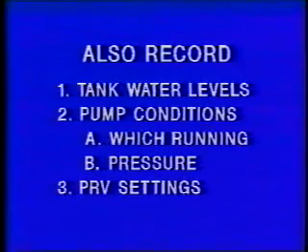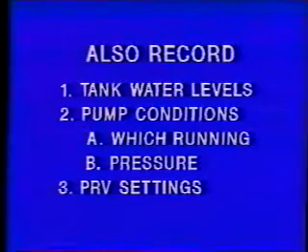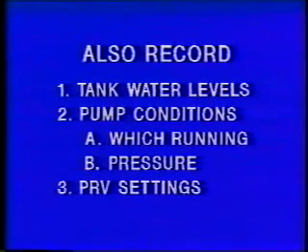While it's not absolutely necessary to record the information you see on the screen, it is very helpful to jot down the water levels on the tank, which pumps are running, and what the settings are and any pressure reducing valves that are affecting the test. This makes it very easy to go back and compare test results with tests run under different conditions. If you don't record this, you may have a problem later on in understanding why the results from two tests are different.